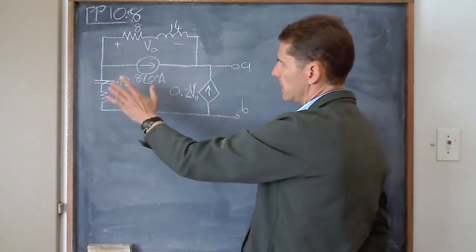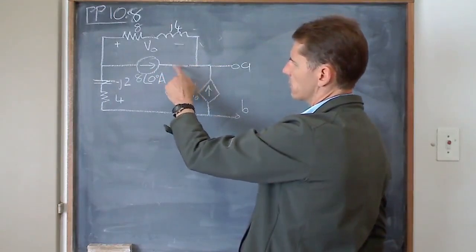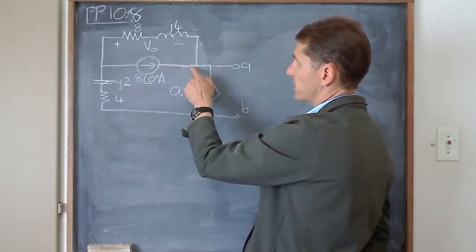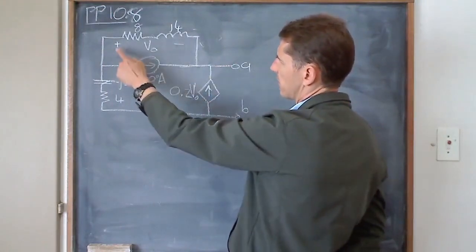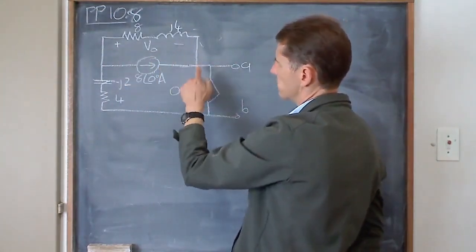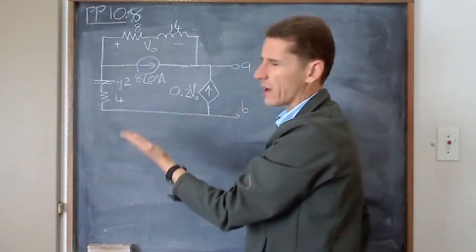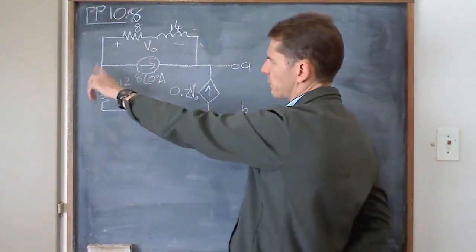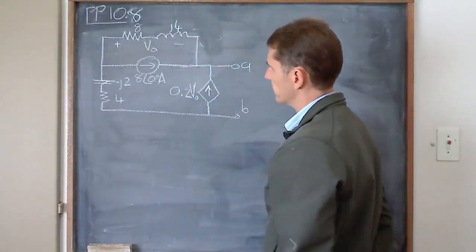Then, quite a difficult one: current source coming in. Where's this current going to go? You've got current coming in, you've got current coming in, so I'm assuming the current will go that way. But now they gave a plus minus, though I suspect that the current will be going in the opposite direction of the polarity. But that's okay, the math will sort it out. And then I've got the capacitor and resistor over here that seem to be hanging around doing nothing.